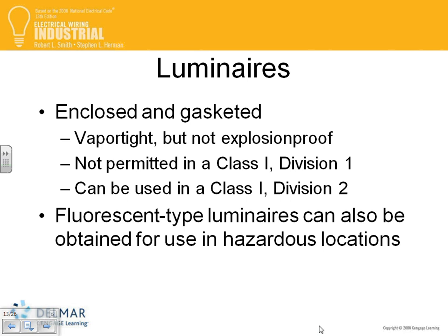Okay. Luminaires. There are two types of luminaires you can use in hazardous locations: enclosed and gasketed. That's the most common one. Enclosed and gasketed, you'll see a lot of pictures. Enclosed and gasketed is vapor tight, but not explosion proof.